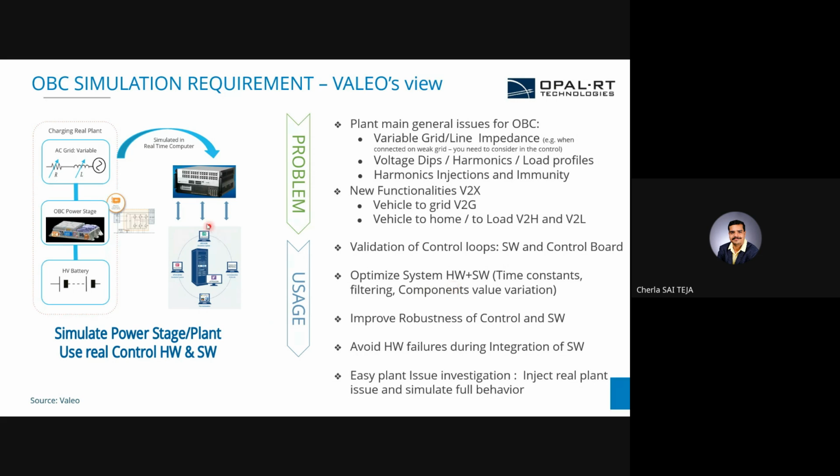So what OPAL-RT did here, we provided the solution, optimized the simulator, both hardware and software, to meet their switching requirements, the time constant filtering, component value variation. By changing the component values here, let us say whenever a switch is closed, the current will be flowing, the on-state resistance will be very low, and whenever the switch is open, the resistance will be very high.